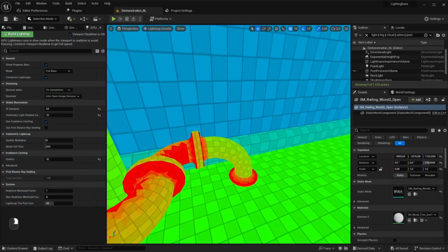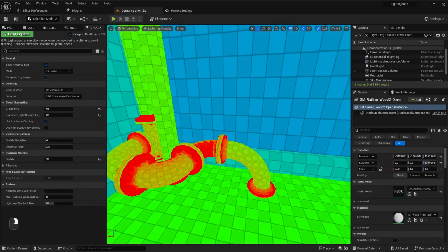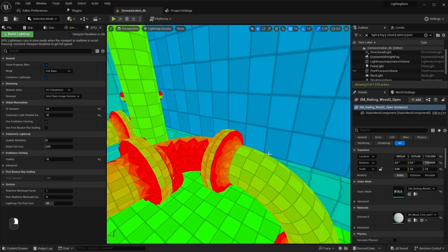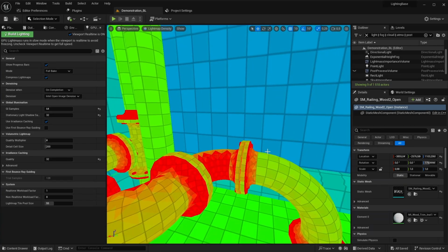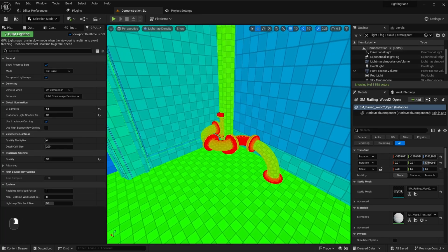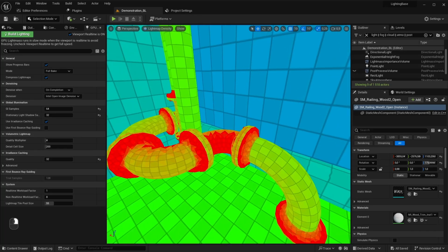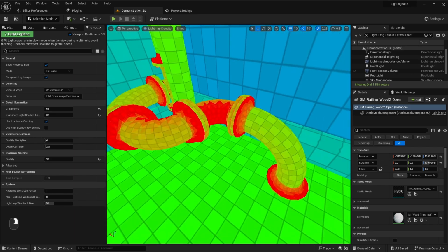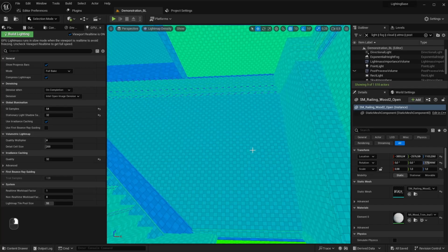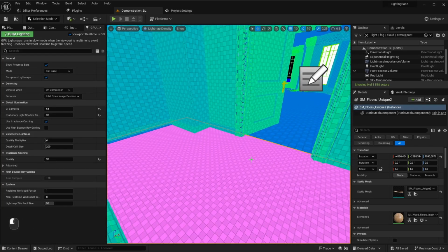When it comes to different surfaces, you might want to have different densities. If you have a lot of small components or crevices or extrusions and things that would convert to smaller areas having more differences in them, then you might want to have a higher light map density, as you can see from this pipe example. But if you're just dealing with very large flat surfaces, you might want to have lower densities there.